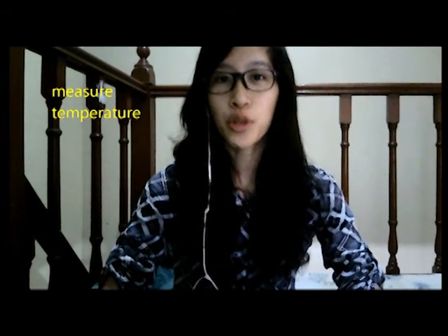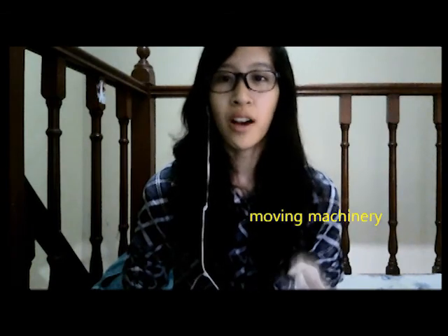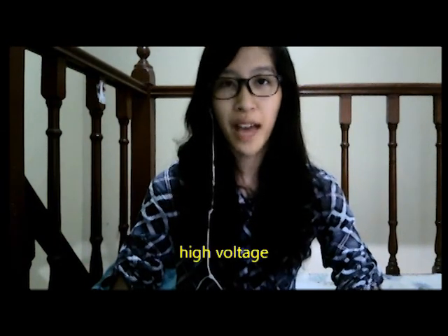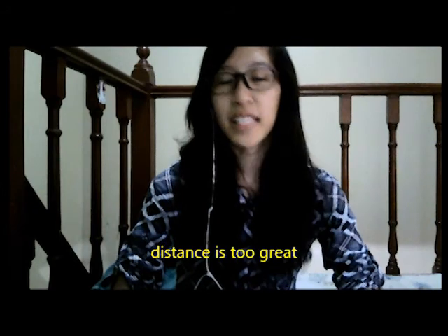Infrared pyrometers allow users to measure temperature in applications where conventional sensors cannot be employed, specifically in cases dealing with moving objects such as rollers, moving machinery, or a conveyor belt, or where non-contact measurements are required because of contamination or hazardous reasons, such as high voltage, where distances are too great, or where the temperatures to be measured are too high for thermocouples or other contact sensors.